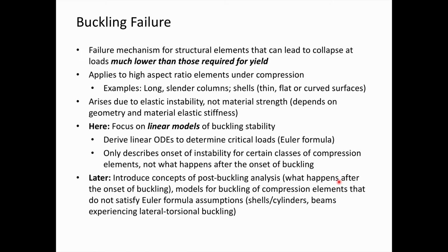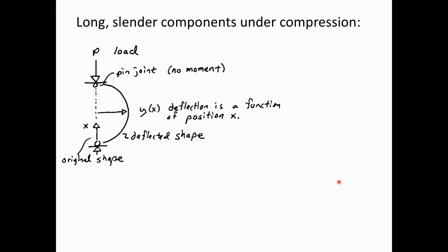on steel structure design. So here's a really simple sketch describing what's going on when we're trying to conceptualize buckling as an elastic instability. Imagine I have some long, slender column and I'm pushing on it with a load P, and x, shown in this vertical direction, is the coordinate that describes where I'm at in the vertical direction along this column that I'm compressing. If I push down on it, then it's going to bow out and